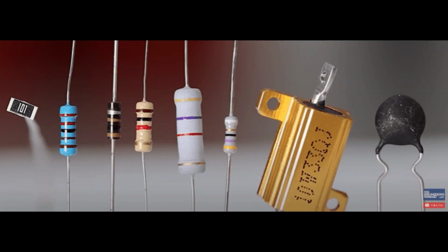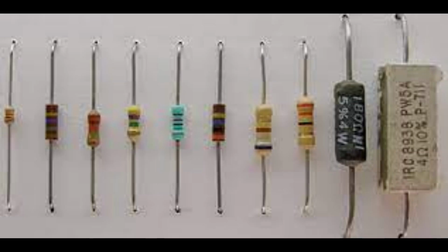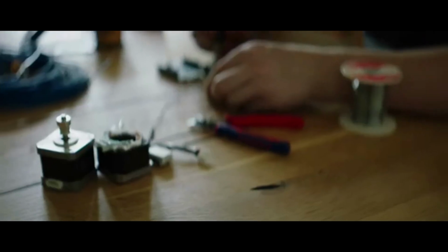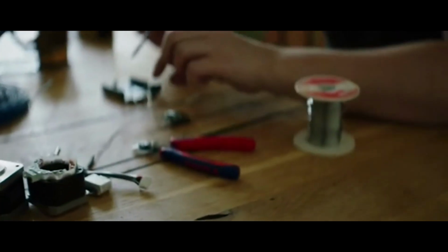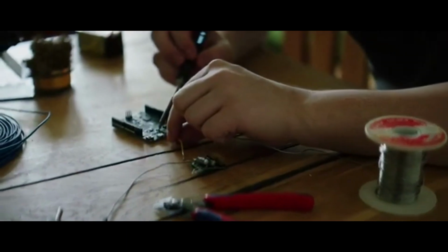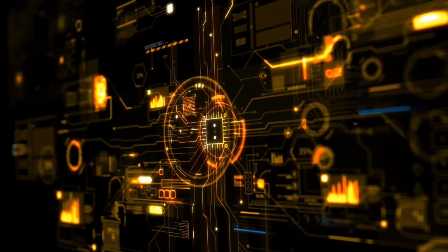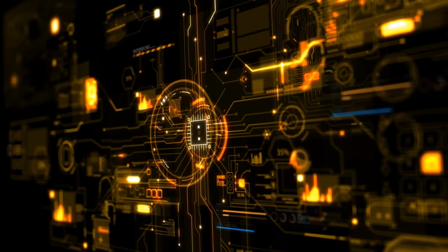Okay, so let's begin. Resistors are electronic components which have a specific, never-changing electrical resistance. A resistor's resistance limits the flow of electrons through a circuit. They are a passive component, meaning they only consume power and cannot generate it. Resistors are usually added to circuits where they complement active components like op-amps, microcontrollers, and other integrated circuits. Commonly, resistors are used to limit current, divide voltages, and pull up input-output lines.